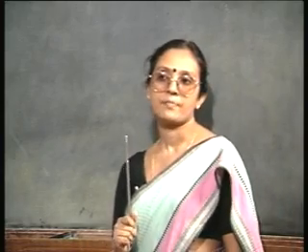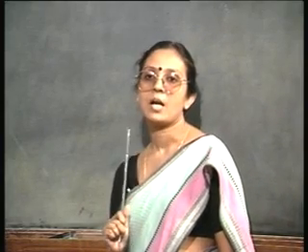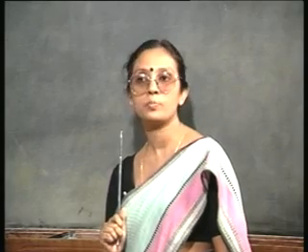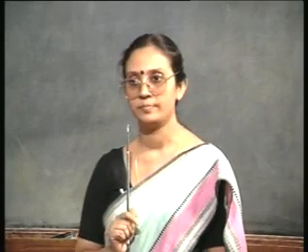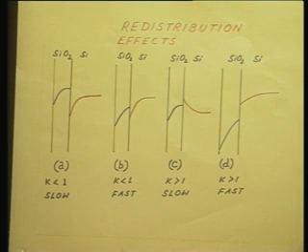In contrast, if I have a heavily boron doped P plus wafer, then the situation I expect is case A, right? Oxidizing ambient, it is a slow diffuser. Remember, boron will be a fast diffuser only in hydrogen ambient. You are carrying out the oxidation, so you are working in oxidizing ambient. So, the case is A. In this case, what do you see?